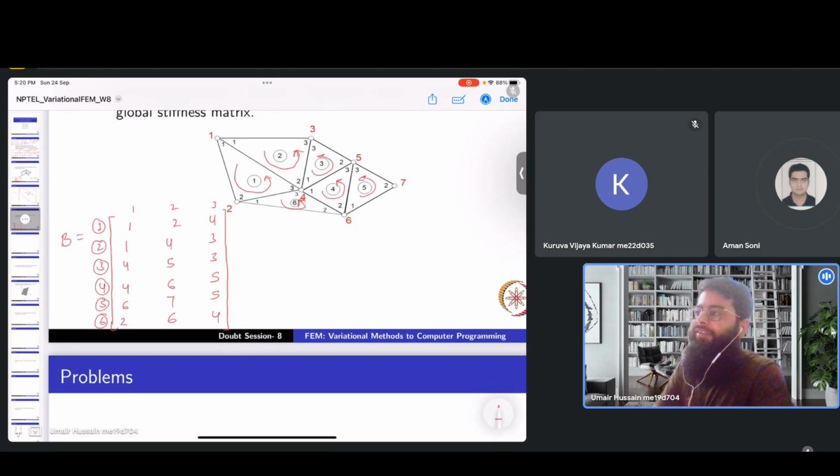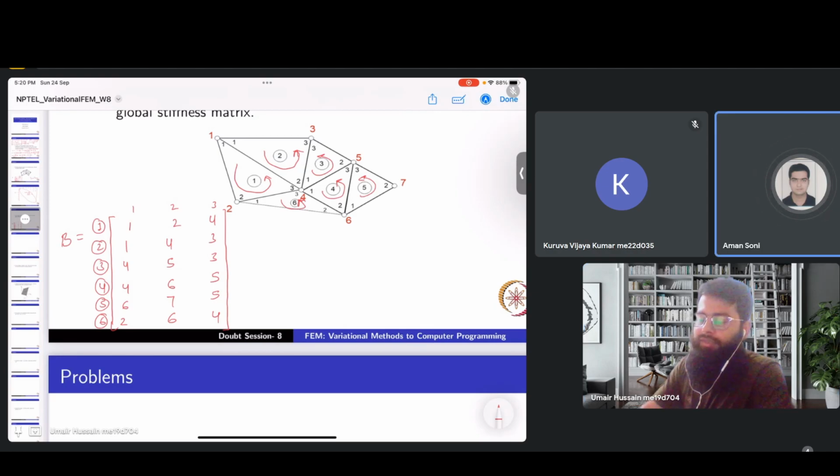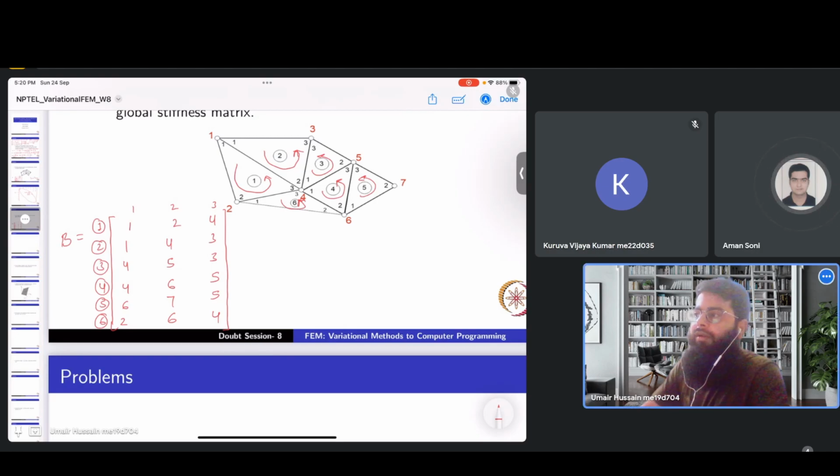So you changed from hex element to which elements? No, I have not changed from hex elements. Hex elements remained as they are. Simply, I renumbered all the nodes that the bolt contained. That's nice. So that's why we try to maintain consistency in numbering, and usually we follow this anti-clockwise pattern.